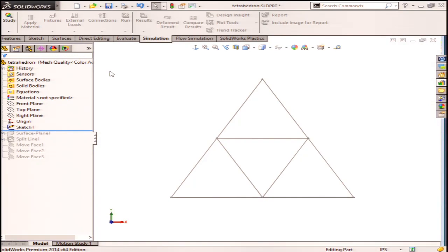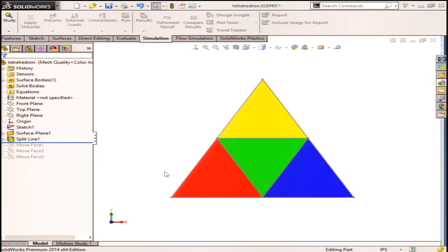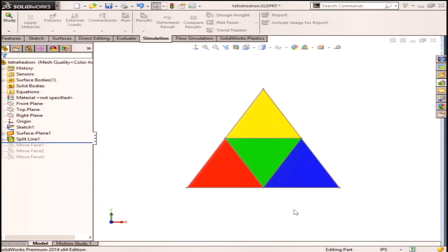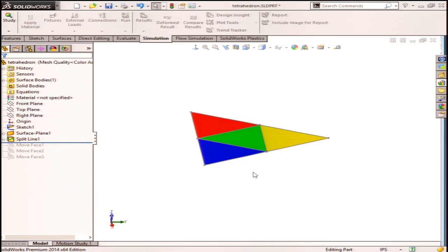here we have a grouping of 4 triangles. And you can see that they're sharing nodes. Every single element, or these triangles, is joined at these points. So here I have a node, another node, here, here, and here. Each one of them is a unique element. So I have green, red, blue, yellow. So this is a shell element that I have here drawn. It's basically just this flat surface. It has a thickness defined behind the scenes, but we're mapping to this geometry with a surface or a planar element.